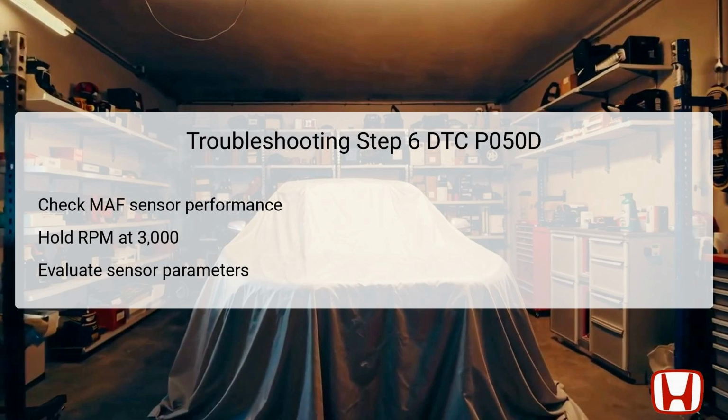Specifically, assess if the current values match the established malfunction thresholds. If the MAF sensor readings fall within the designated limits, it can be deemed functional, leading to the next step in the troubleshooting process.